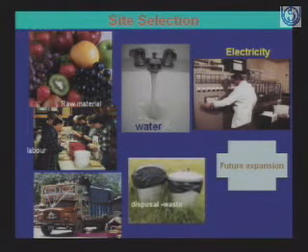The fourth block, block 4, talks about plant layout and site selection. Before you lay out a processing plant, it is very important to know about the site in which you want to lay down your processing factory, and the number of factors which you have to consider. You have to consider the availability of raw material, whether you have good raw material available around, good cheap labor, transport facilities, water. Water is very important.